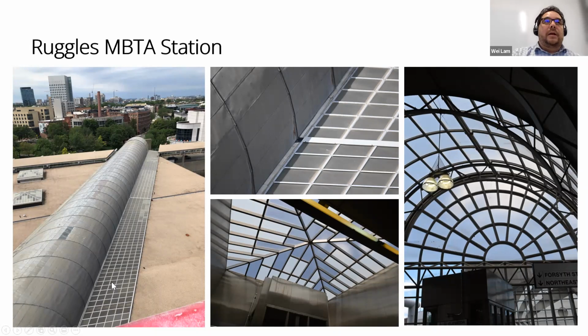But they're finally getting around to fixing this, and the idea here, at least for the slope glazing area, is probably to incorporate a system with polycarbonate panels, eliminate all of the purlins here, and get a polycarbonate panel that will run continuously and provide a better flow for drainage transfer across onto this roof. There has been some consideration of installing a gutter at the base of this barrel vaulted roof, between the barrel vaulted roof and the slope glazing.